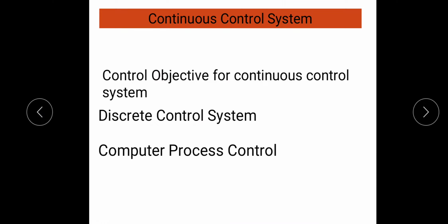In this table, dear students, we will discuss regulatory control. The first one is regulatory control, which is a control objective of continuous control systems. In regulatory control, the objective is to maintain the process performance at a certain level or within a given tolerance band of that level. The performance measure, or index of performance, is calculated based on the output of several variables. The disadvantage with regulatory control is that compensatory actions can only occur after a disturbance and not before.